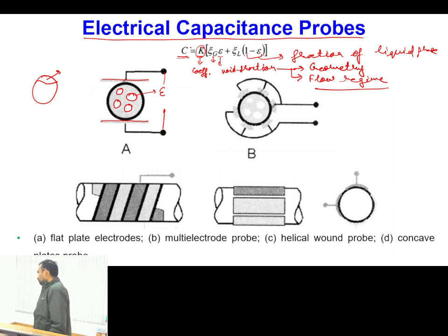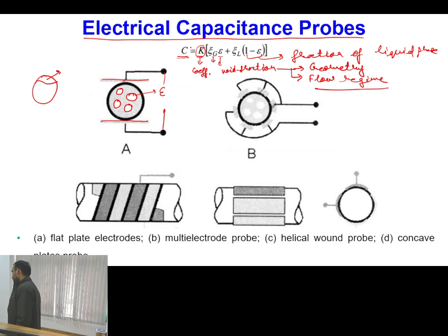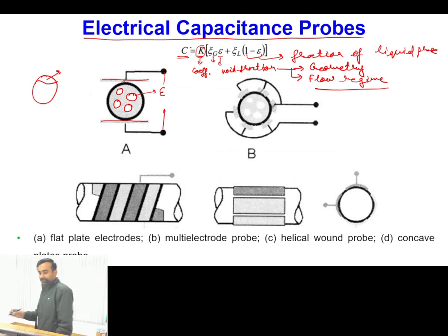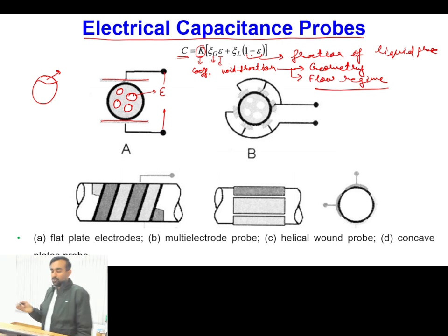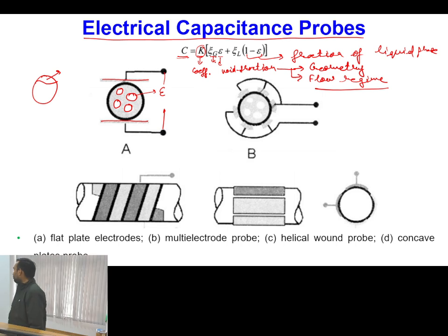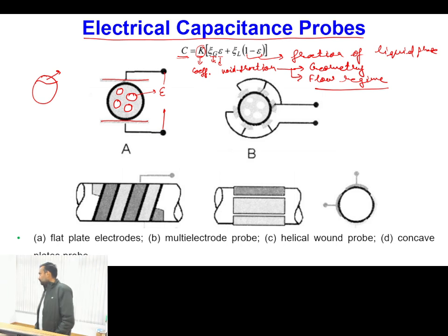Okay. These methods, can they only find whether bubbles are present or not in the liquid, or can they differentiate between two liquids like kerosene and water? Yes, it can differentiate if their dielectric constants are significantly different. Because in this particular method, we are talking about the capacitance based approach, and capacitance value is a function of dielectric constant and phase fraction. So if the dielectric constant of that particular liquid combination is significantly different, it can be used. So for some, like the optical probe method, yes.